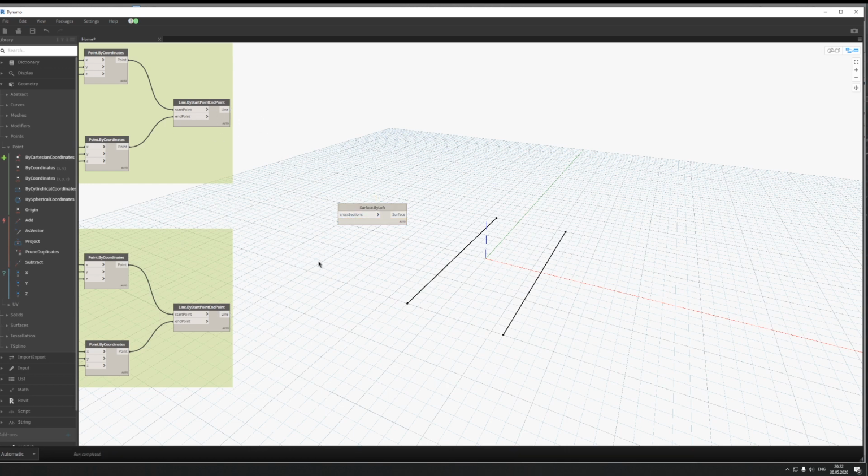I know some of the people already know how to do that, but I'm trying to explain to everyone. So how can we combine these lines? For this, we need to use a list. We should create one list to combine them like one element. So just List Create, this is what we need, enter. We can place one item here. Let's connect our item here.